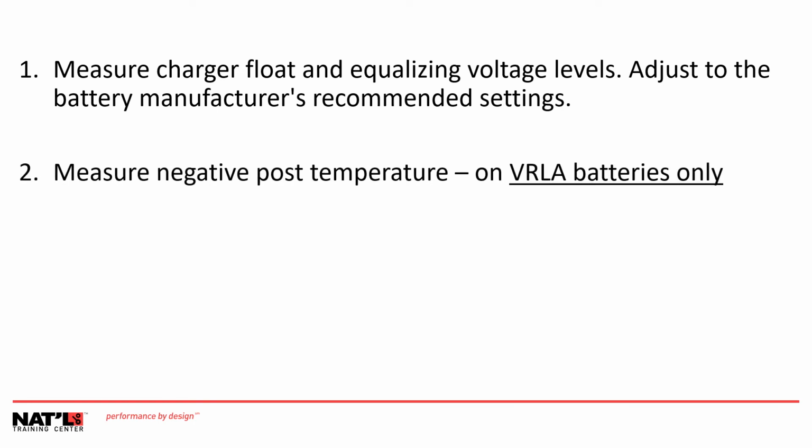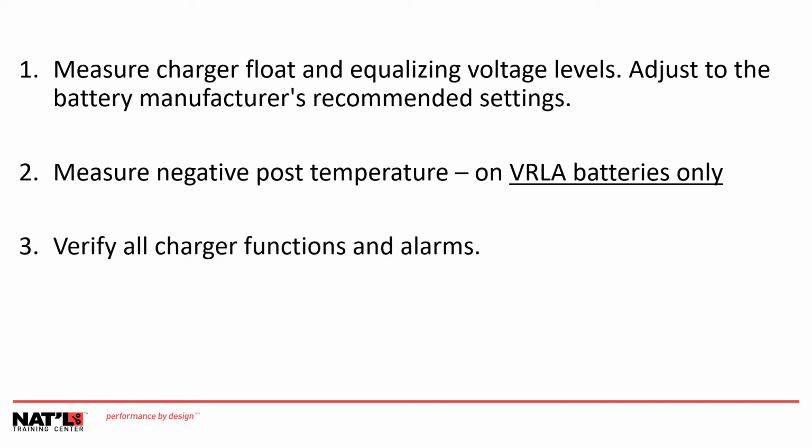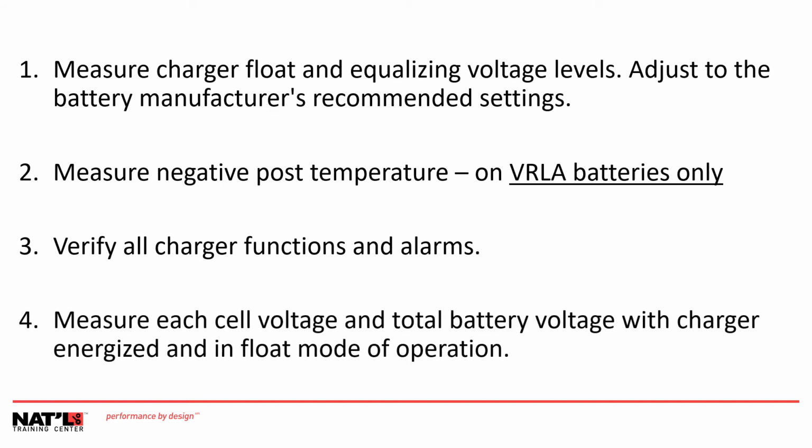Measure negative post temperature on VRLA batteries only. Verify all charger functions and alarms: ground alarms, low voltage alarms, AC alarms. Battery chargers vary a lot from manufacturer to manufacturer on what alarms they have and what those alarms do. You should go to the manufacturer's instructions and verify all existing alarms.